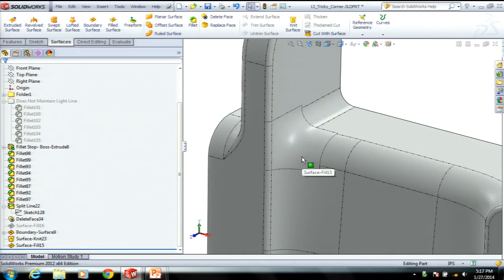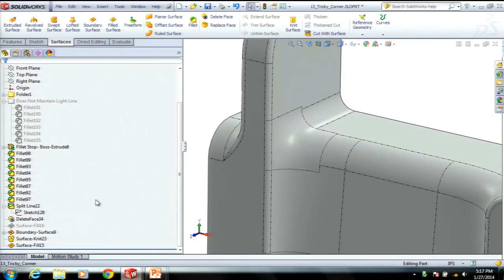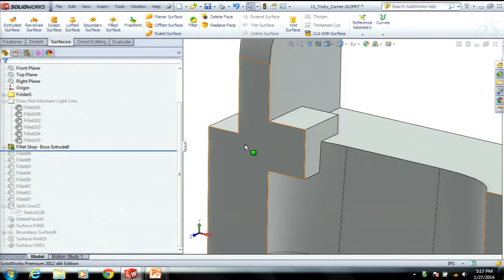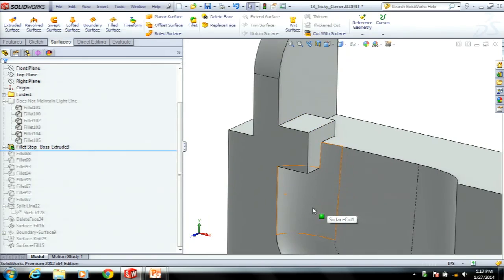Yes? Just curious why it looks like the top of your block that you subtracted looks somewhat arbitrary. Why didn't you select the top line of the radius instead? Because I didn't know how big the block would be until I added the fillets. That's actually a great question. So in this example, I made the block oversize at first to get the fillets that I knew I needed to have.